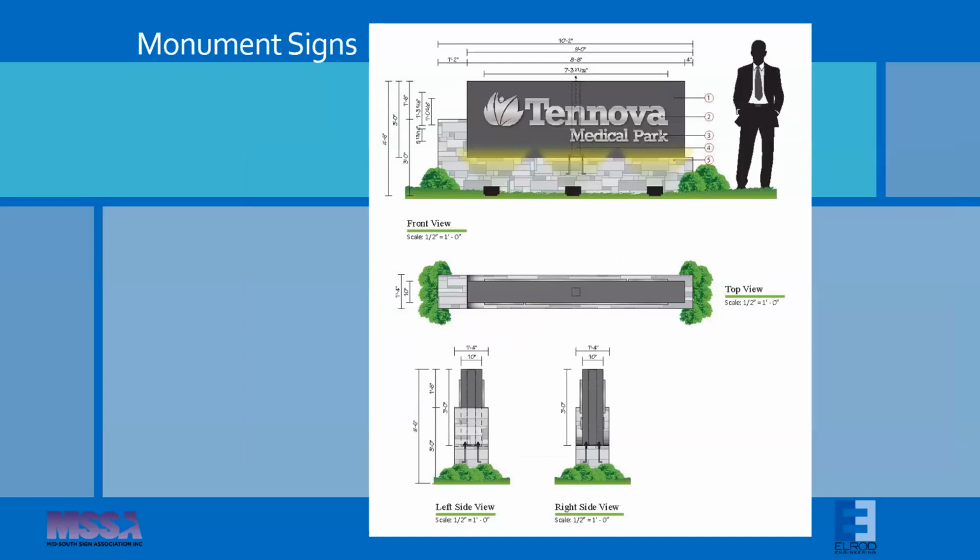This is another monument sign that shows an interesting challenge that many people wouldn't consider. As you can see from the middle of that top graphic, the support pole in the middle of the cabinet is going to be anchored to the CMU base, which seems like a good idea and is certainly logical. It makes sense, except for one thing. Once we started laying out the design and placing the CMU blocks into that foundation, we realized that all 4 of those embed anchors are located in the same CMU block with 2 in each cell. Per the building code, we are only allowed to consider 1 anchor per cell. So this suggested design doesn't work.